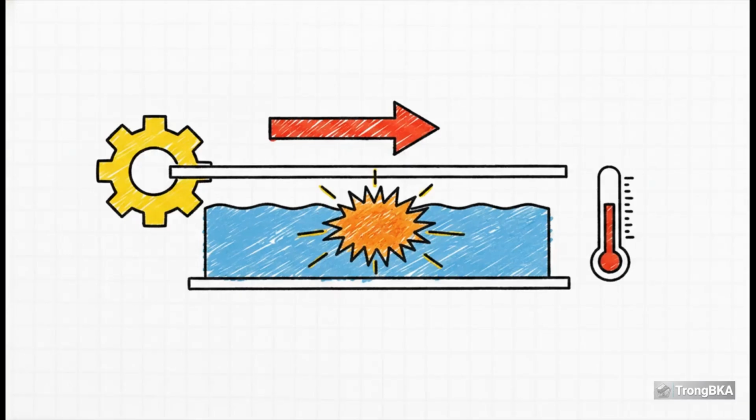And honestly, we need all the help we can get because polymers are tricky. When we input mechanical energy to shear the sample, that energy has to go somewhere, right? It's often dissipated as heat. We call this viscous heating. In a sliding plate setup, for example, the maximum temperature literally spikes right in the middle of the fluid. So why does this matter? Well, because viscosity changes with temperature. The very act of moving the polymer generates heat, which then changes its viscosity mid-flow. It's a totally chaotic variable, and it perfectly illustrates exactly why we need such robust math and CFD to track what's actually happening in there.